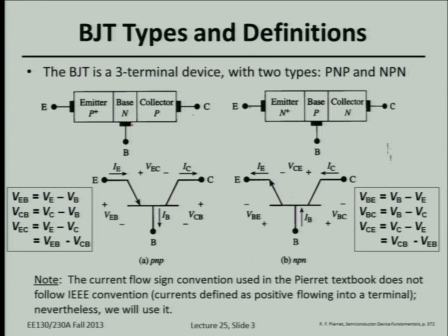All right, so remember in a transistor, what we do is we have one control terminal, where we're controlling the current or the voltage. And that determines the current flowing between the other 2 terminals. So usually we consider the control terminal in a BJT, the terminal that connects to the middle region, the base. Okay? So we apply a voltage or a current to the base, and that controls the current flowing between the other 2 terminals. The 2 other regions are the emitter and the collector.